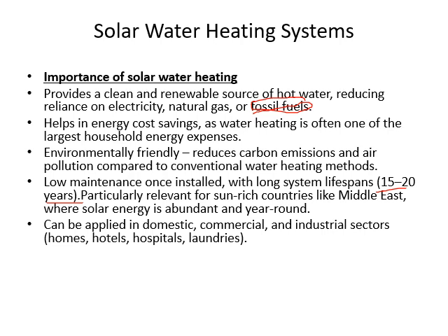My professor, under whom I did my PhD, installed a solar water heating system for the airport's dishwashing purpose. Because at the airport, many flights are coming and they are clearing out their cabins, all the used up dishes and everything. So they installed a solar water heating system on the top of Changi Airport, and that saved a huge amount of electric energy, because for washing the dishes around 60 degrees Celsius is good enough to kill all the bacteria and germs.